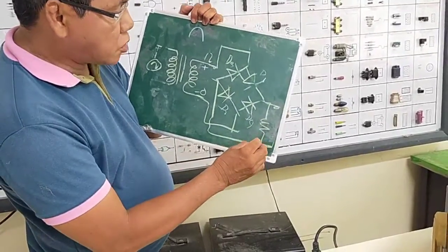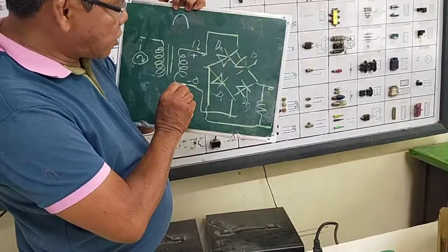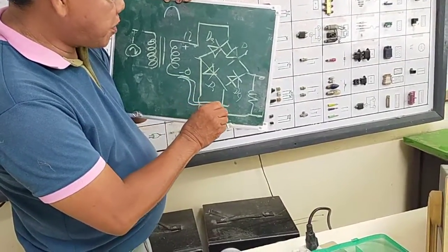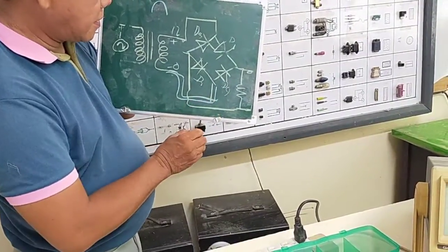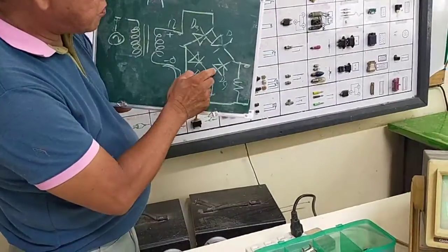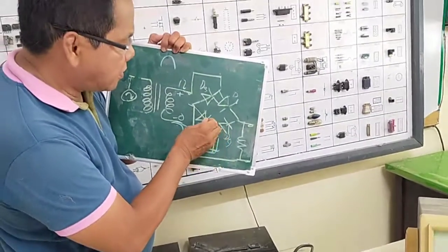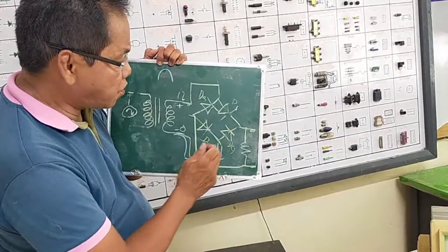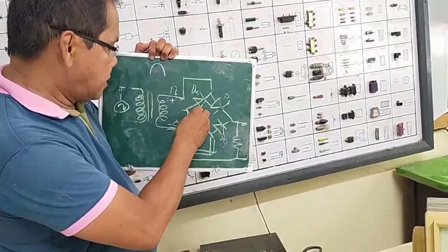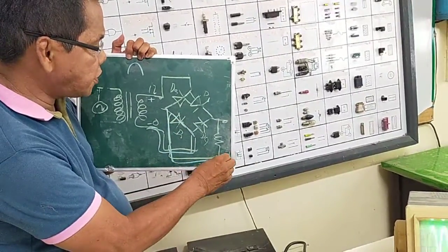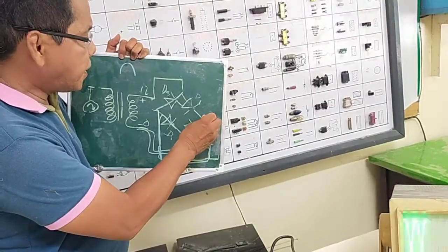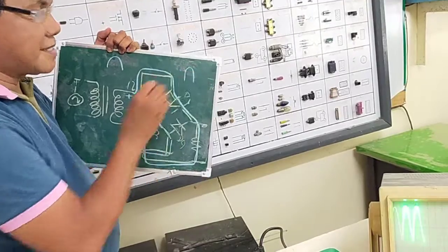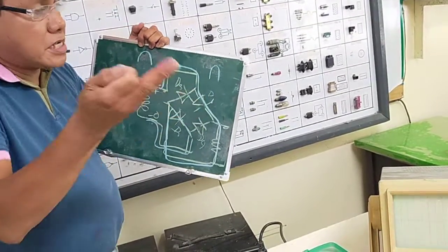So, it goes like this. From this zero or negative polarity of the transformer's winding, it goes like that. So negative, it shouldn't be here. It should be here, because the cathode is forward bias to this negative side, not this one, because this is the anode. So it goes like here, then going down, then passing the RL, then D1 going to the positive side. So the output goes like this. The first half cycle is allowed to pass.